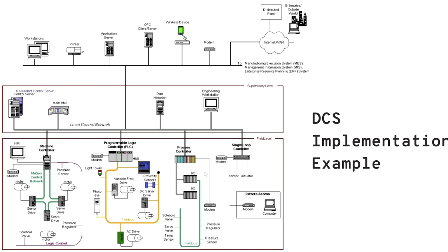You may have a series connection to a remote access here that can be in-field connection from the engineer. Another controller that can be remotely accessed as well. So here, they may be different parts, but they're distributed, and they're connected through a local control network that goes all the way to a main link here, workstation, application server, OPC, and so on, that may or may not connect to the enterprise network, or you may connect to the internet, right? And well, of course, this comes with its own security problems.